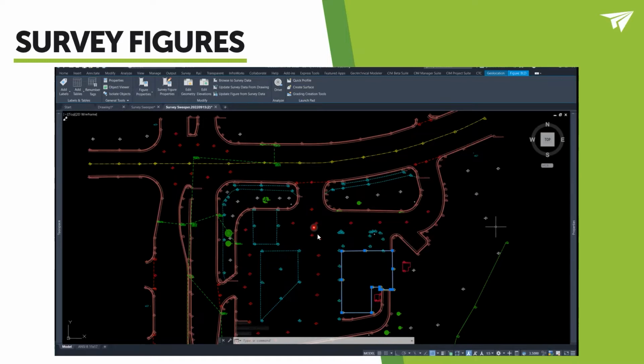We have some here in the middle that are probably concrete shots, but you'll also see that we have some COGO points that are stringed together by lines. We have some buildings here. We also have some curb data. All of these surveys are processed through the survey database, and these are automated through CAD. So it saves us some time connecting dots and getting this linework created, as well as makes it easy for us to enter these as a surface and create a surface for our site.